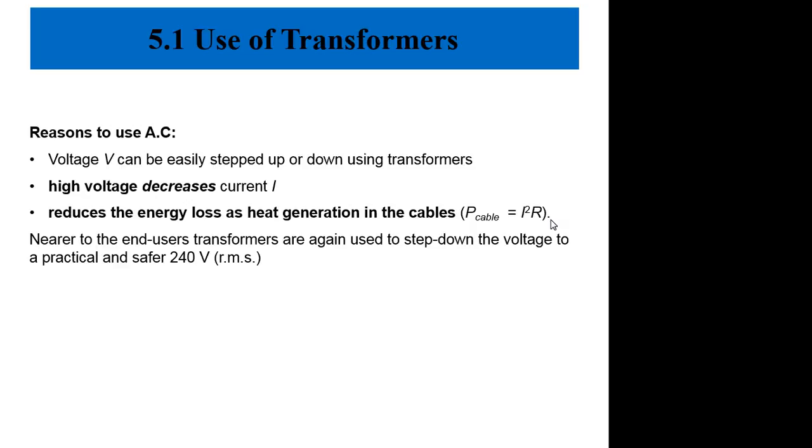You look at the power loss equation. You don't want to lose it, so you send it at a very high current. You send it at a very high current, you lose money. So what can you do? Can you decrease the R? Yeah, you can, right? But how do you decrease the R? R equals rho L over A.